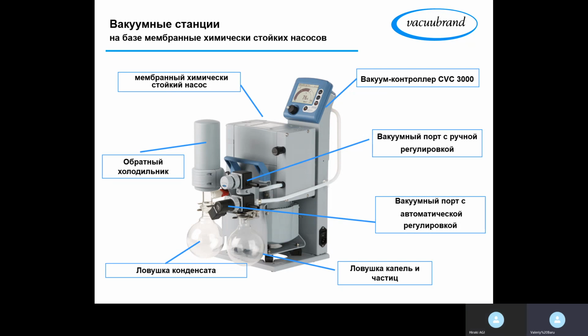I can give you one good example. That was when I learned that this is a very important option for the vacuum pump. That was back in 2010 when I sold two 20-liter rotary evaporators to a customer, and they were evaporating THF solvent, which boils at about plus 64 Celsius.